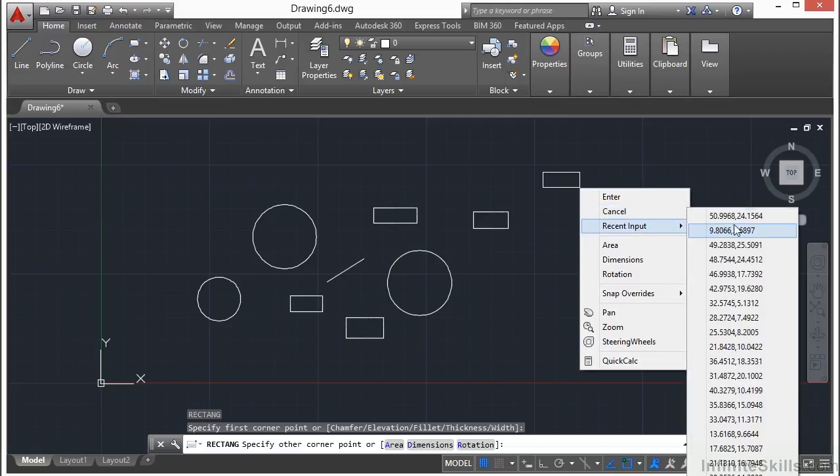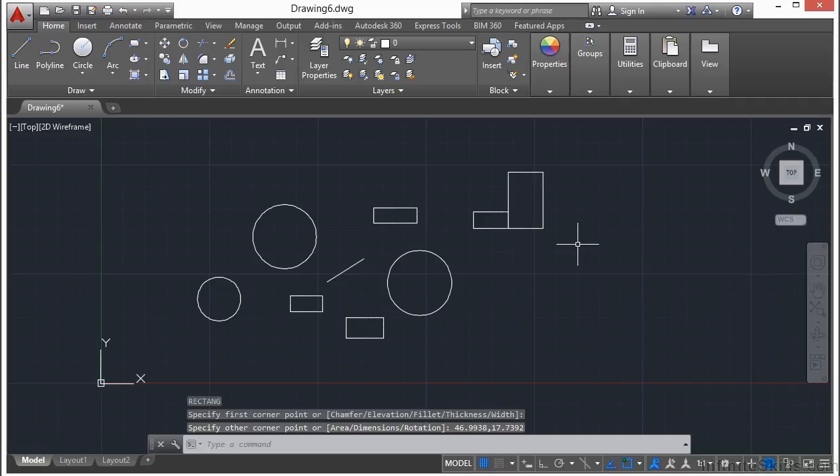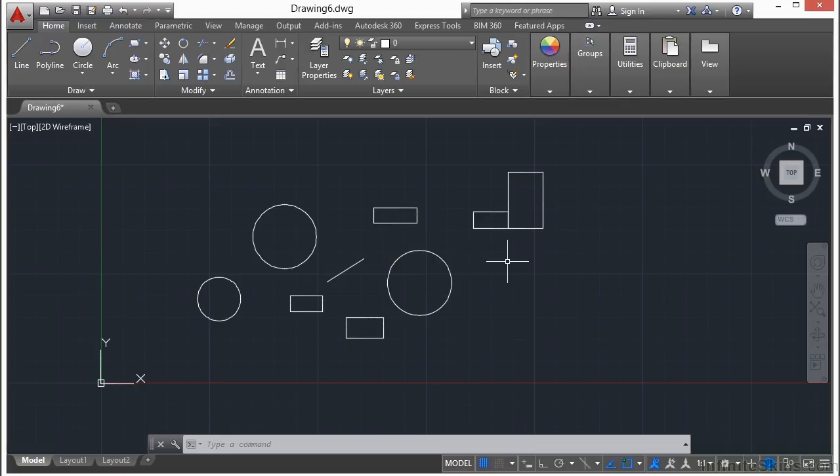It's an option. And a lot of these are just coordinates. So I can click one again, and it popped me right to that same coordinate. Now that's really cool if you're trying to draw objects to the exact same spot, or you need a similar circle or length or diameter or something like that. A lot of times you don't have to retype that same radius again or that same coordinate point. It's all right there. So it makes it very easy. So this is just a few tips and things to keep in mind when you're working with AutoCAD.